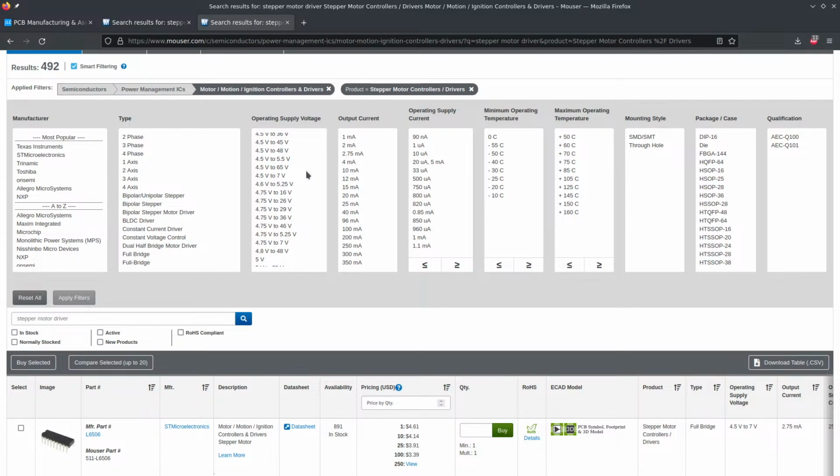So we set it to say we want 1 amp of current through the coil at full tilt. It's going to apply that 36 or 40 volts or whatever to it until the current increases to 1 amp, and then it turns it off. And when it moves a slight bit below 1 amp, it turns it back on, and it creates this very messy looking signal in voltage, but in current it goes up and stays pretty much at what it's supposed to be by turning it on and off.